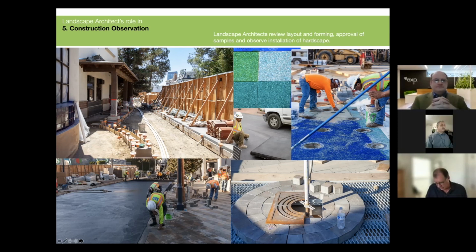As we said earlier, one of the differences in the theme park world is we get to install very large plant material. Well, that's not without its own challenges. First, it usually needs to be installed before the paving. That's not typical for most contractors. So we require them to locate the trees by survey in exactly the right location and exactly the right elevation.